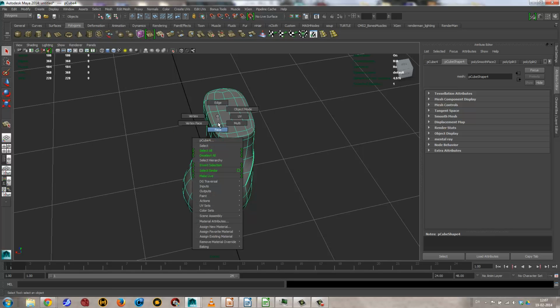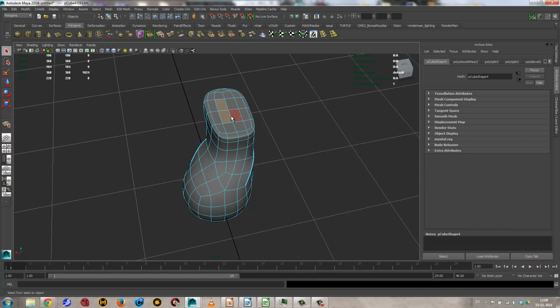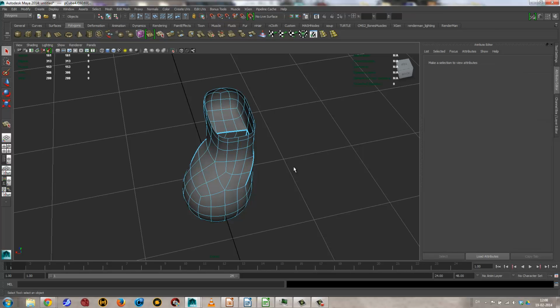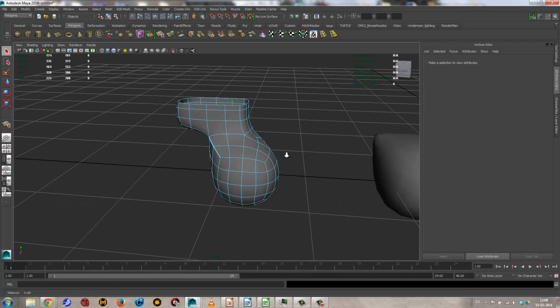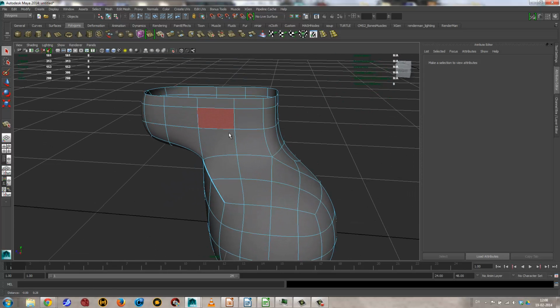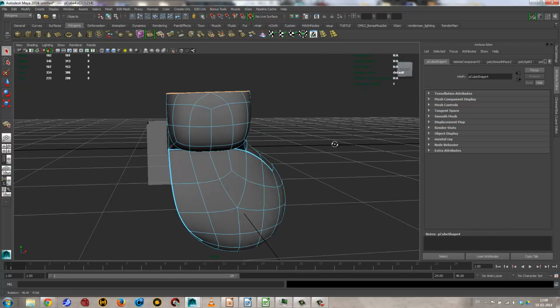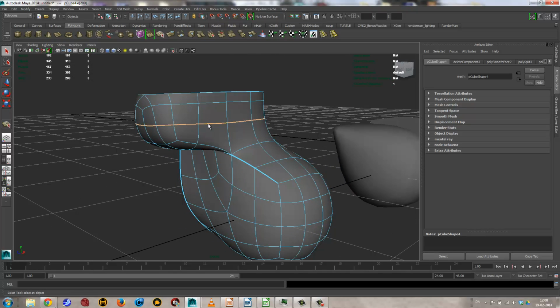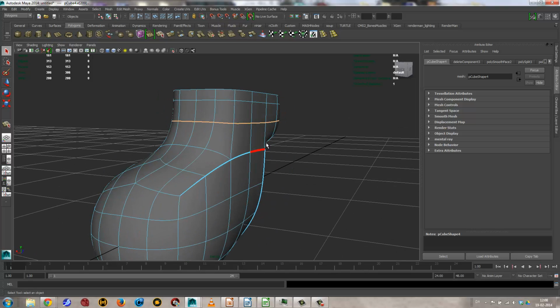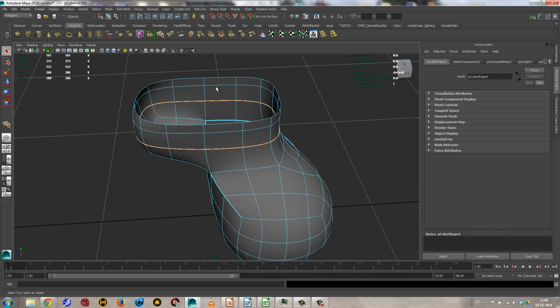Another thing is I can use the extrude as well. See if I just select this and then go Shift and the larger than key, I can then grow selection and then press delete. So now I've created an open shell. If I then grab edge and double click the edge, that will extend the edge to the whole border edge. In this case, if I click this one, it will find the edge flowing around using something called edge loop. We'll get back to that.